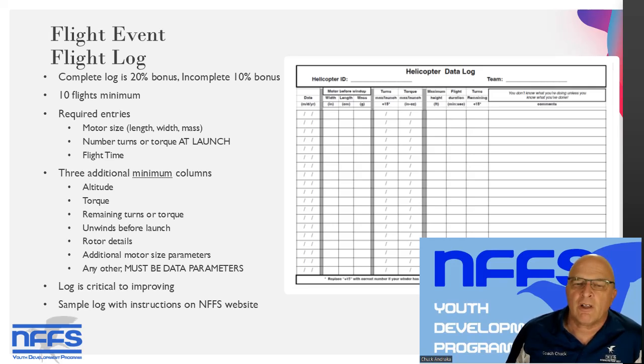Number of unwinds before launch. You can really turn this rubber quite tight and you risk breaking your motor stick. So you may want to unwind a little before the flight, and you may want to record how many turns you unwound before the flight. If you're experimenting with various rotors, you may want to have details of your rotor, such as pitch, number of blades, chord, and so forth.